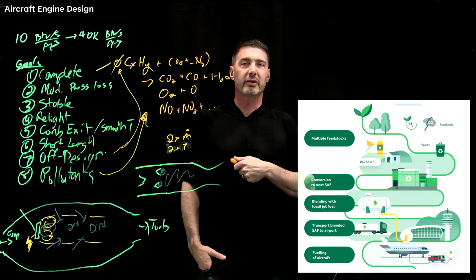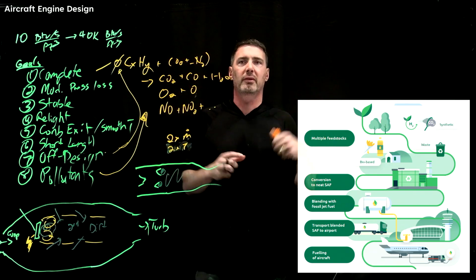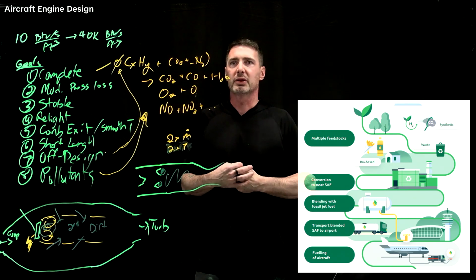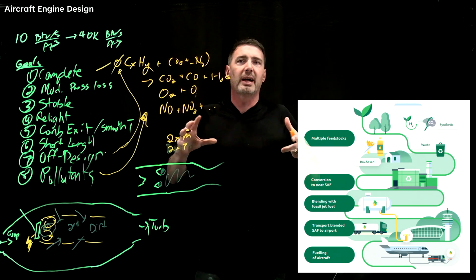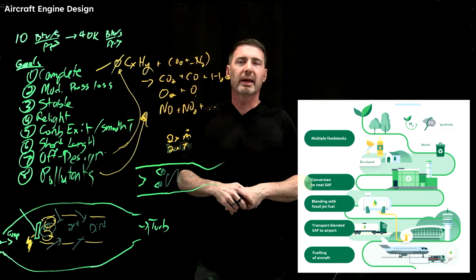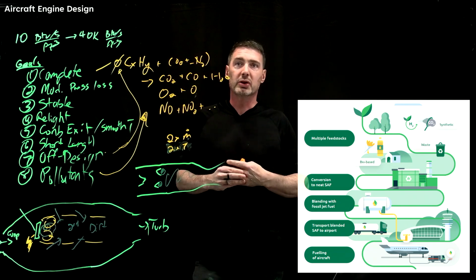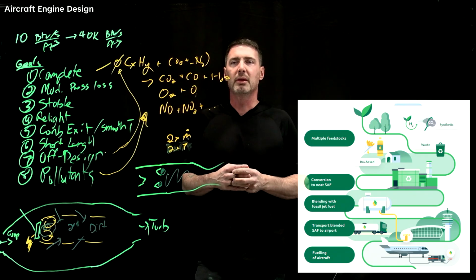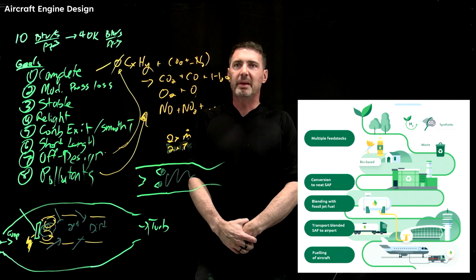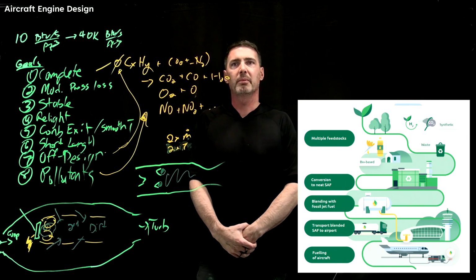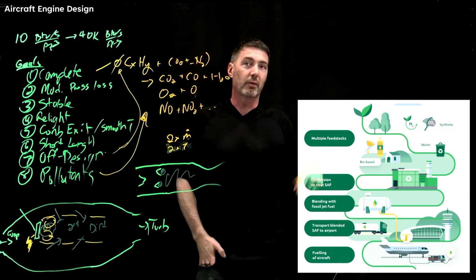People will talk about hydrogen aircraft. The challenge with hydrogen aircraft is just that hydrogen is not very dense. I talked through this during the Kuchemann lecture series, and it's just that your vehicle designs are not going to go far. Look at the space shuttle, the size of the big orange tank. Any of these hydrogen aircraft, if they're fielded, are going to be regional. They're not going to have enough range to, say, cross an ocean. Hydrogen aircraft may be part of how we reduce our carbon footprint, but for those long range flights, it's certainly going to be SAF or nothing.